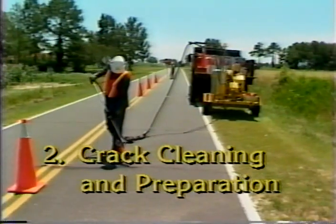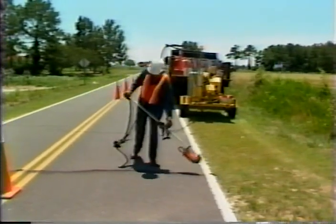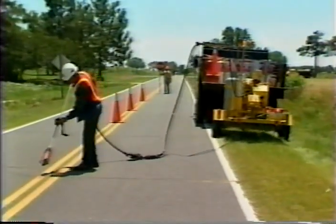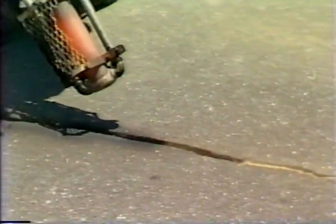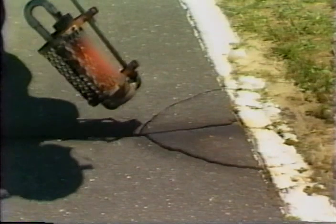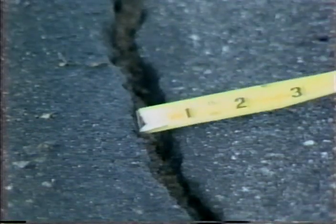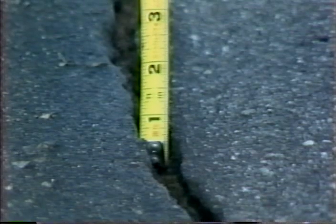The second step is crack cleaning and preparation. Cracks must be clean and dry for sealants to bond to the pavement. The best method of crack cleaning and preparation is the use of a hot air lance. The hot air lance removes dust, sand, and other debris from the crack and also dries any latent moisture which may remain in the crack. It also heats the asphalt surface and softens the asphalt binder, aiding in bonding of the sealant. Any organic material is also burned away. Clean cracks of all loose debris to a depth equal to or slightly greater than the crack width.